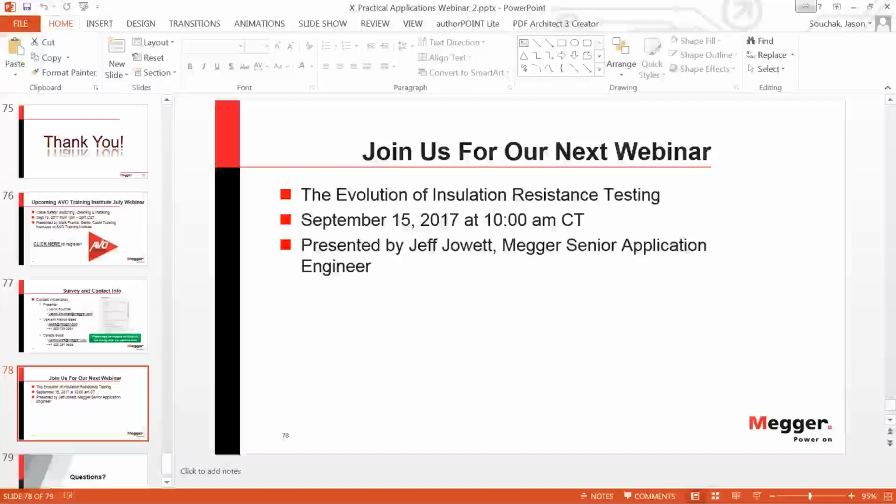Okay. Thank you, Jason. Henning, do you have anything to add to that? Yeah, in terms of the tan delta testing, and I don't know exactly the number, but it's in the few nanofarads that you must have as minimum cable capacitance in order to measure tan delta. So it's not microfarads. You don't need microfarads, but you need something in the nanofarad area. I think maybe 8, 10 nanofarads. Different manufacturers have slightly different levels there. As a minimum length or the minimum capacitance, which translates into a length of cable, in order to do tan delta testing.